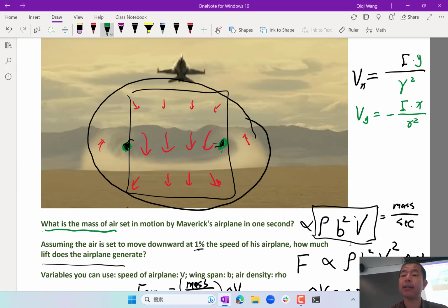First of all, it's rotational in the sense that the x velocity is proportional to y and the y velocity is proportional to minus x. That makes the flow field exactly rotational. Then the magnitude of the velocity, I think there is a 2 pi, is inversely proportional to the distance between the center of the vortex and the location in the flow field. Both together make the region with significant velocity proportional, in both height and width, to the distance between the two vortices.